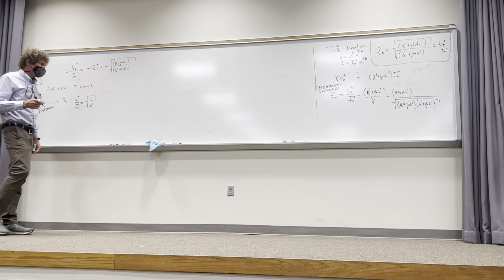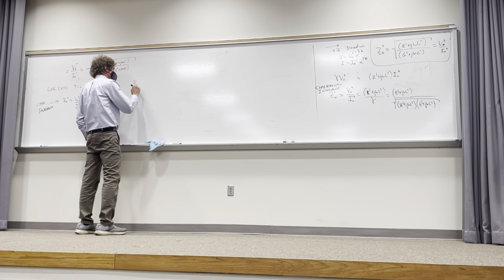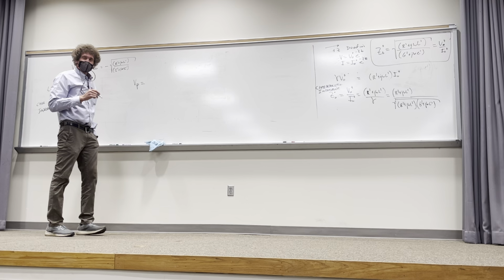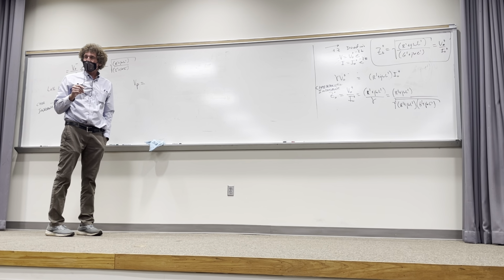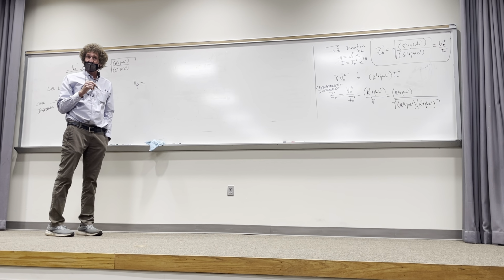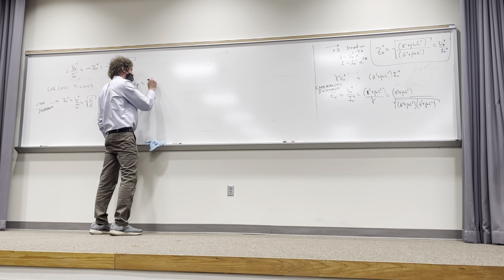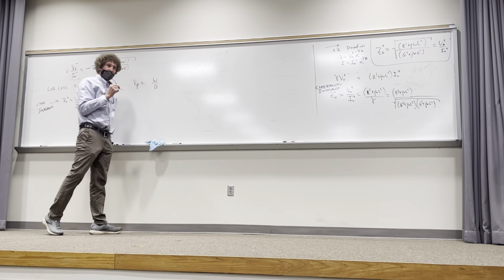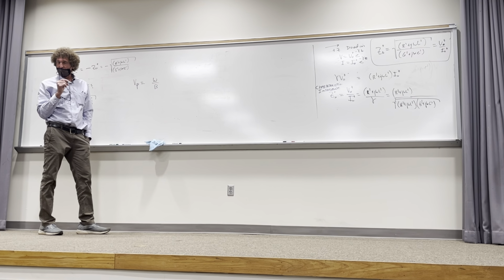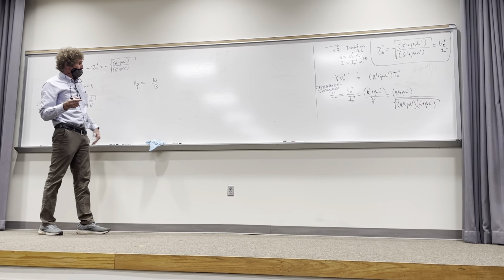Something else. Do you remember what phase velocity is? Do you remember the fundamental definition, anybody? I developed this last time, but I didn't give you a problem with that. Remember how I got it? I took omega t minus beta z and I set it equal to a constant. And I took a derivative of that term with respect to t, right? And I solved for dz/dt. Do y'all remember that? And I found out phase velocity was omega over beta, didn't I? Remember that? And when you found that, the key thing here is beta, isn't it?